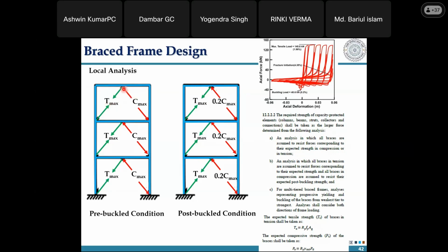So what you do is you remove the braces, remove the external earthquake force as per the response spectrum method and equivalent lateral force. You will have these combos prepared. IS 1893 gives this code wherein it gives the way you will arrive at the expected value of maximum capacity of the tension and compression brace.